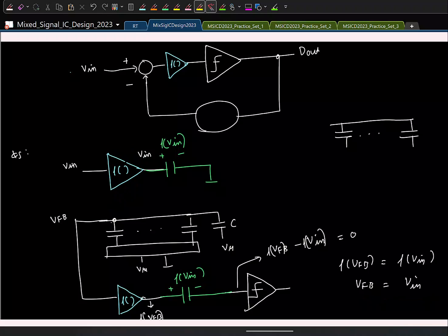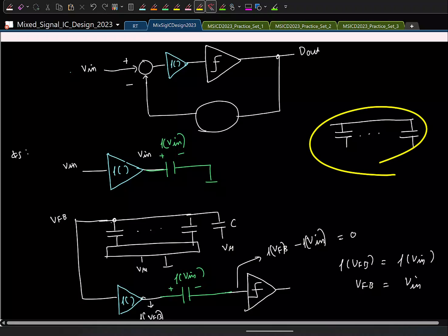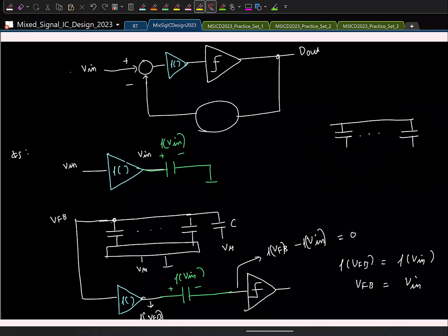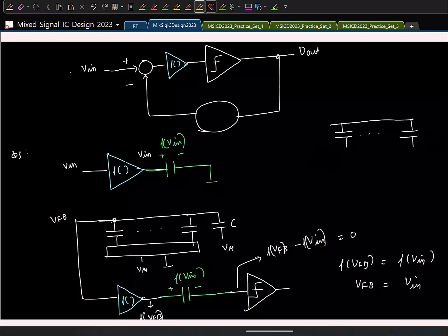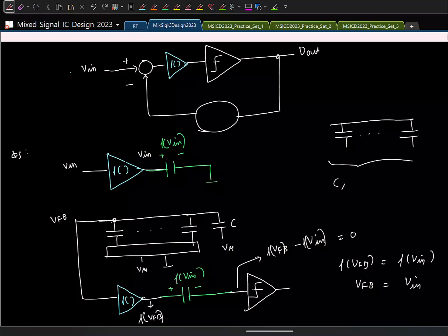Now it works on another level, which is the following. In our conventional SAR ADC implementation, the input was sampled onto the same capacitor as the capacitor we are using for generating the reference voltage. And there we saw that for getting good matching between these capacitors, we need to use a minimum capacitor for the unit, which means the total capacitance in this array was much greater than what was required by kT/C noise.